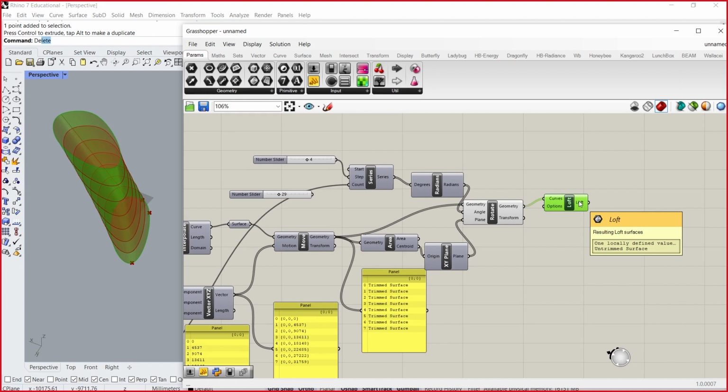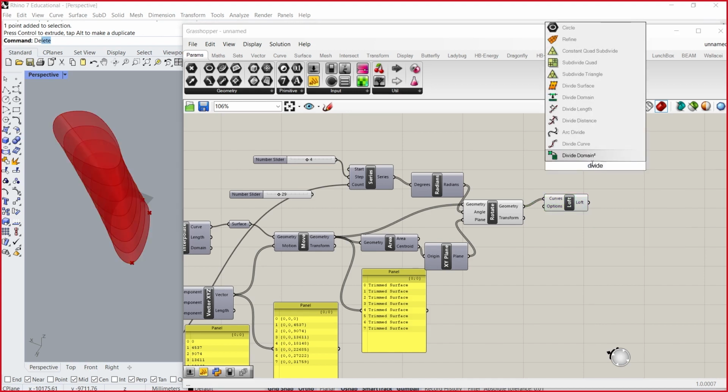All this hard work and our outcome is only one thing. It's one surface. Okay? So remember what I said earlier, we're working with NURBS. So things have local coordinates. This is actually a good thing. What we have is 10 floors, 10 geometries, and one surface wrapping all of it around using the loft. Because it's a NURBS geometry, I can start using the local coordinates.